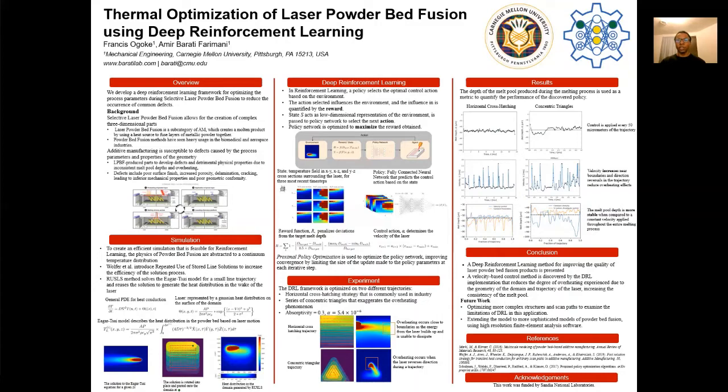So in this method, in general, to advance the solution by some time delta t, we apply Gaussian convolution or Gaussian blur to the solution at time t minus delta t to approximate the heat diffusion far away from the laser. And the Eagar model is solved for time delta t, or if it's been encountered before in a previous case for the same process parameters and same delta t, we simply reuse that solution, and we superimpose it to the solution at time t minus delta t after the diffusion operation has been applied to generate the solution at time t. And in their paper, they show that this method is very similar to finite element results, but significantly reduces the computational expense associated with it.